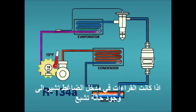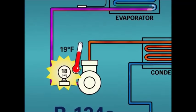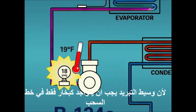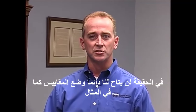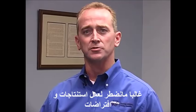Because the values at the inlet of the compressor indicate a saturated condition, we know we have a problem. In this case, we have floodback, because in the suction line, the refrigerant should only exist as a vapor. So far, in our example, we've been evaluating temperatures and pressures in an ideal type of system. In reality, we don't always get to locate our gauges as we did in this example. Oftentimes, we're forced to make deductions and assumptions.